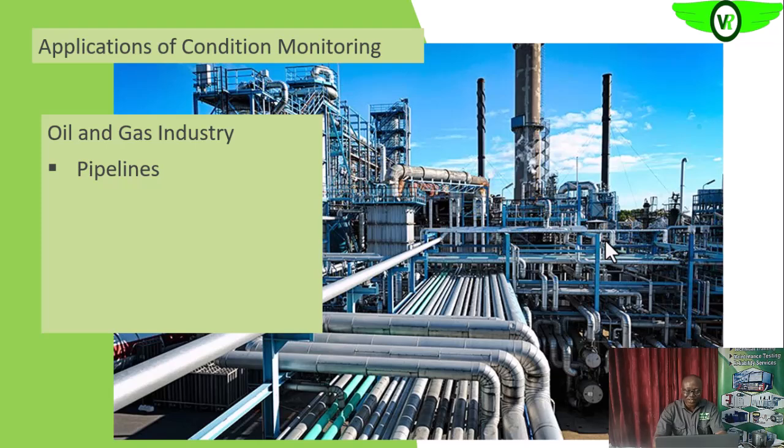There are technologies that will assist us. Ultrasonic is one, thickness gauging is another. Infrared thermography can also assist us in some instances, especially in areas where fatigue could be established.